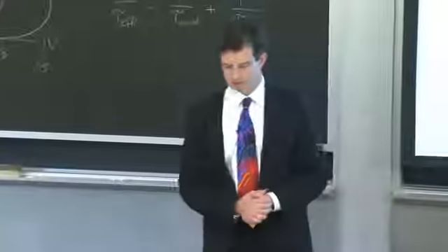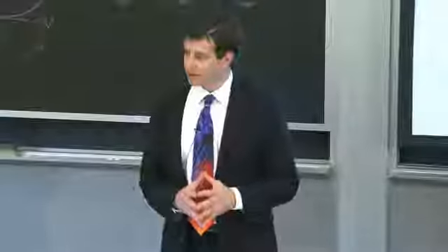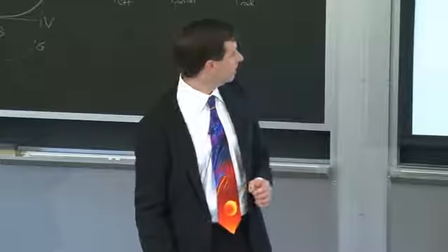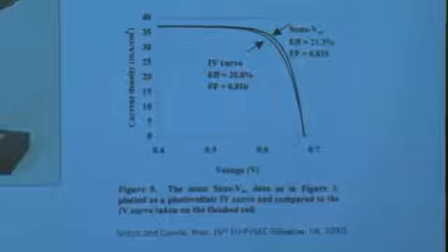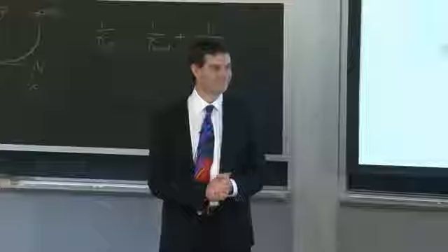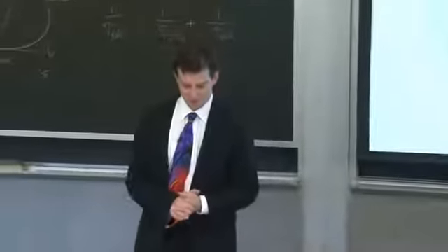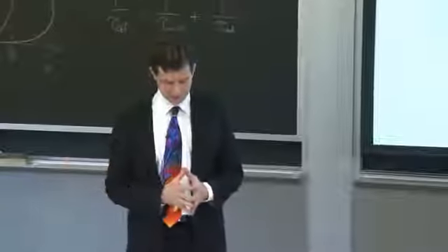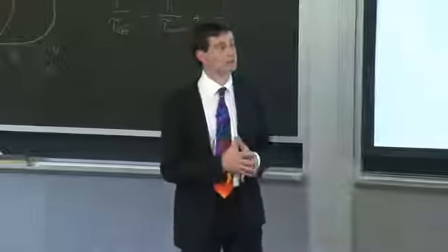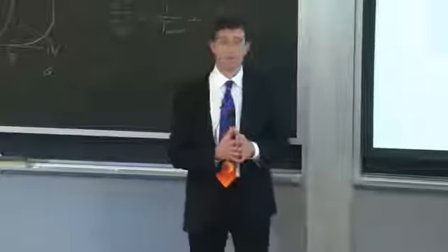For a silicon-based device, the majority falls within the specified regime. Down here, actually right here, sorry, on this diagram, that little spot right there, that is a small calibration solar cell of known short circuit current and open circuit voltage. So that's used to calibrate for other silicon devices. If you're moving away from silicon, that becomes an issue. Correctable. You can measure the spectral response or the spectral irradiance of that light source and compare it to the solar simulator and do the normalization accordingly.